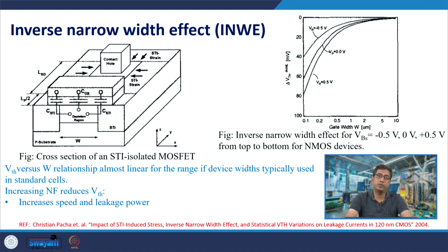Then there are also systematic variations. So, systematic variations are, as we will see in examples, variations which can be modeled with respect to layout level parameters or device level parameters. Now, can these systematic variations be taken into the circuit design methods? For example, we have had this effective current model derivation for, suppose, an AND gate. Then can the systematic variations be taken into account and the effective current value be modified accordingly and taken into design considerations a priori? So, that is the approach that we will be following in today's lecture.